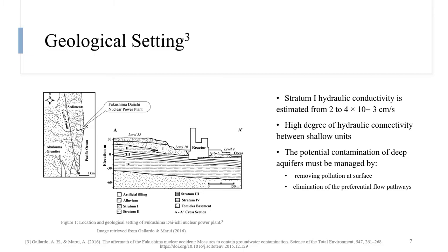The precipitation is on the order of 1,550 millimeters per year, and considering that the evaporation reaches about 700 millimeters per year, the aquifer would receive about 540 millimeters of recharge from rainfall alone. And this is really important for the groundwater discussion later. The bulk of the groundwater currently flows through the sandy layers of stratum 3. And this unit constitutes thus a leaky aquifer fed both from upper units as well as by inflows from the western margins of the premises.